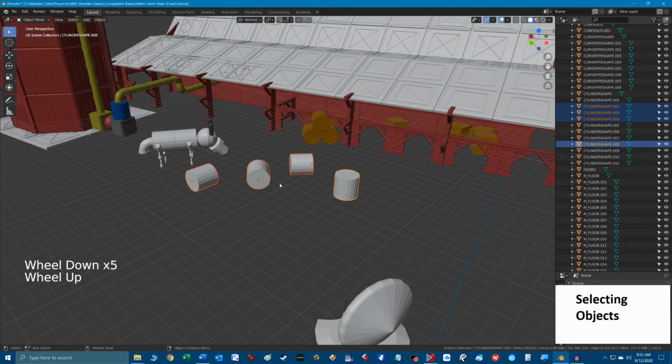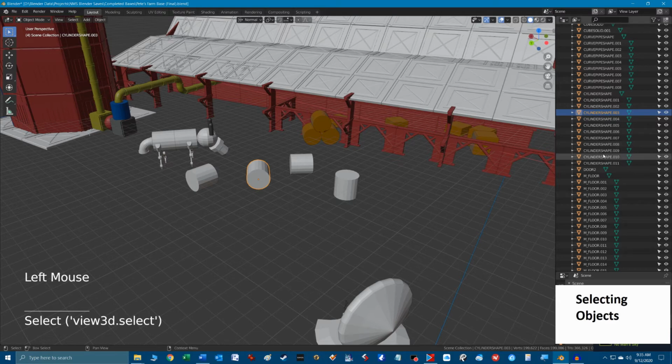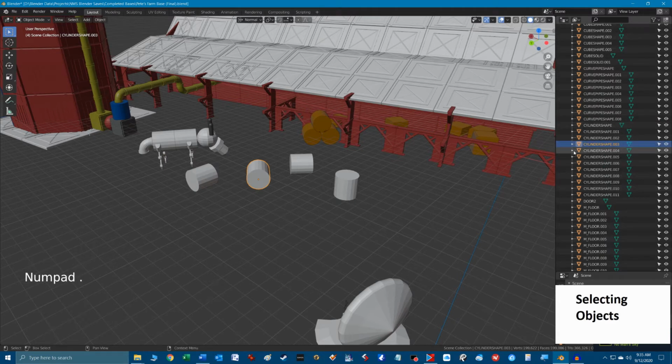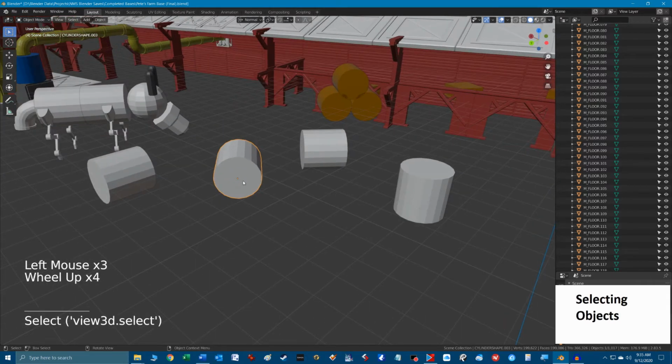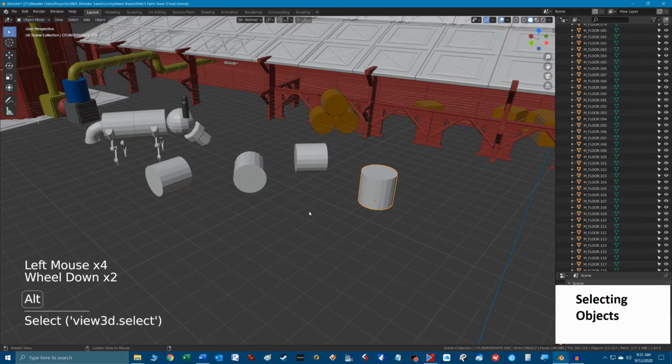If you select an item in the main window, you can also move your mouse over the Scene Object list and hit the numpad period key. This list will scroll to focus on that object highlighted by orange. You'll also notice a small orange point when you select an item. This is called the item's origin. All objects have an origin point. The object's origin can be used as a reference point when aligning, rotating, or sizing an object.